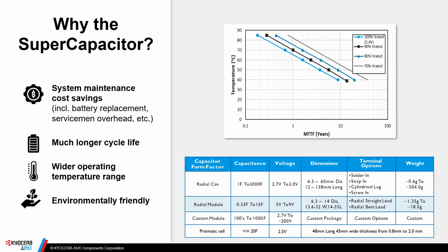improve the MTTF dramatically. So the general statement of the 10 degrees C doubling the life and the 0.2 volt doubling the life is relatively close. Of course, there's predictors and calculations that are possible, but this is a good rule of thumb, the guide.